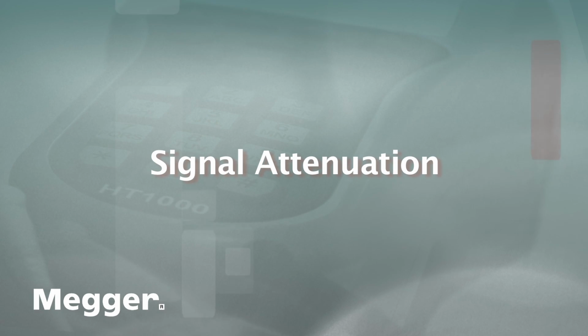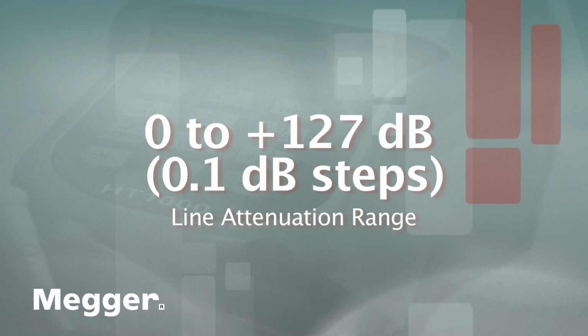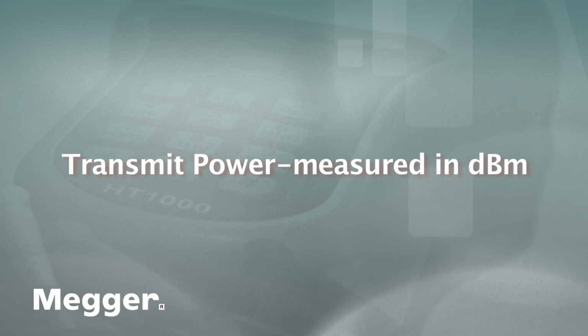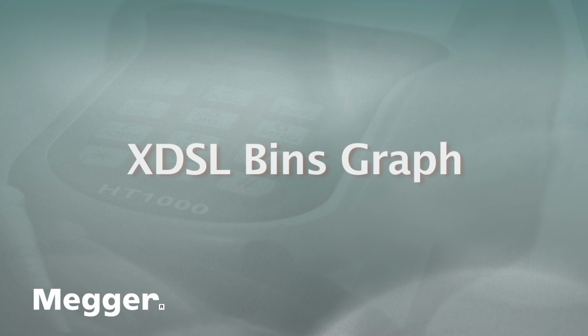Signal attenuation. The measured difference in total power transmitted and total power received over all subcarriers during showtime. Line attenuation ranges from 0 to plus 127 dB with 0.1 dB steps. Transmit power. Value of the total output power of the modems measured in dBm.